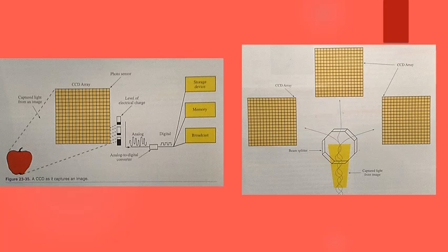The CCD converts the individual packets of electrical charge into a series of analog signals representing the level of light amplitude at the photosensor location, and an analog to digital converter, ADC, converts the series of analog signals to digital signals. The digital pattern can be sent to a block of computer memory to be stored as a still image, recorded to CD or DVD, transmitted across a computer network, or broadcast using the existing assigned television bands.